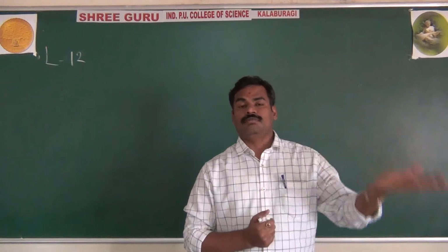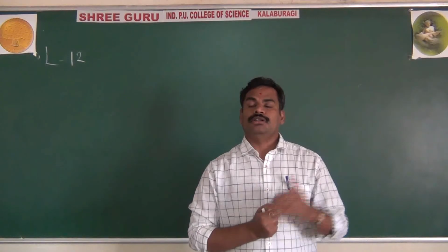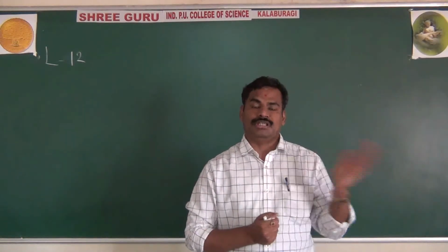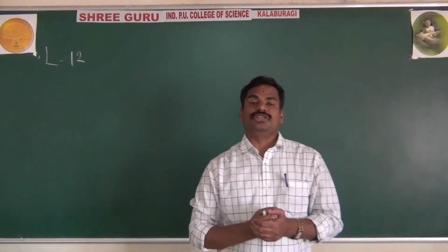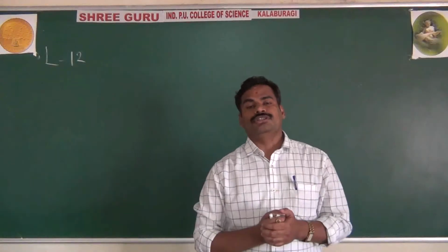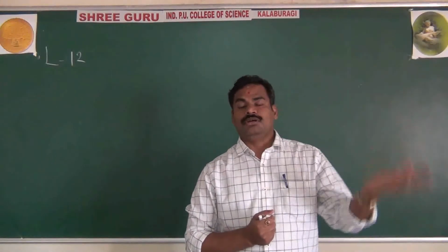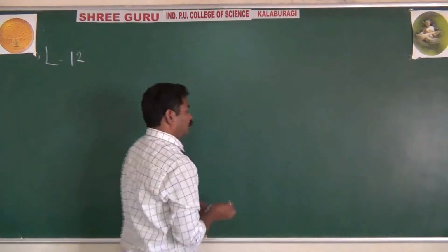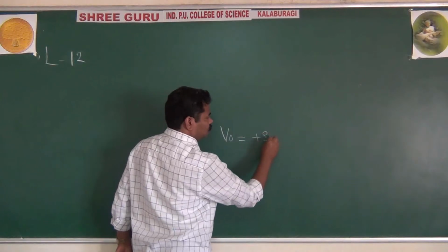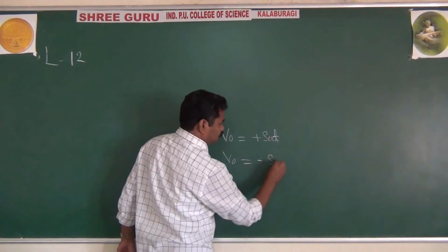You also already studied one of the most important applications of the comparator: it can convert analog into digital signals. It means if you apply an analog input, you will get a digital output. Because, as we know, the output of a comparator can take only two values: positive saturation or negative saturation.